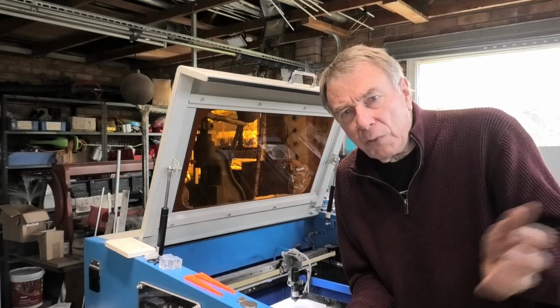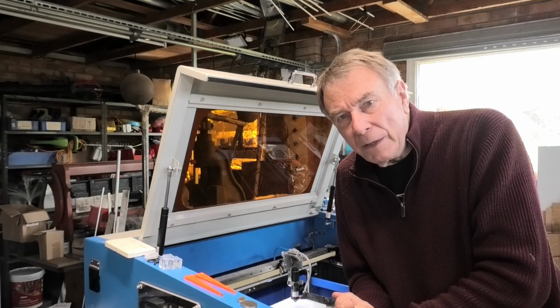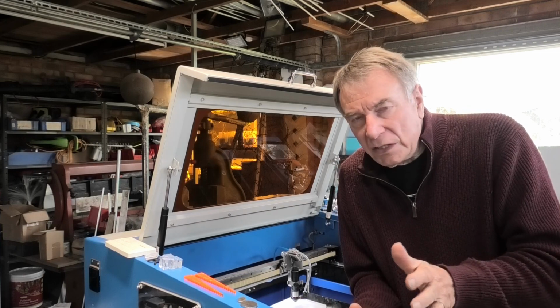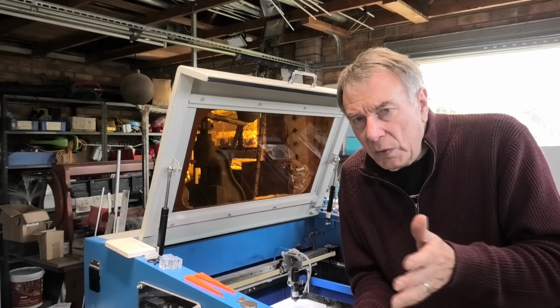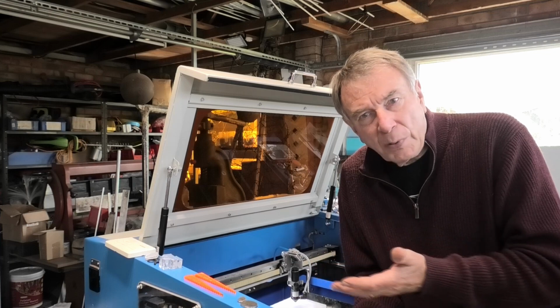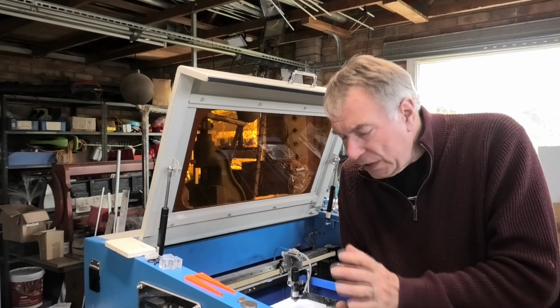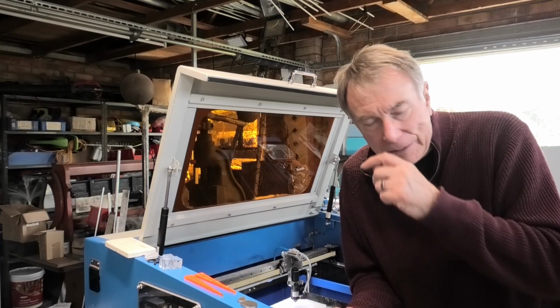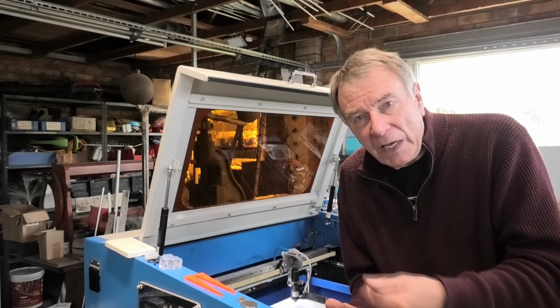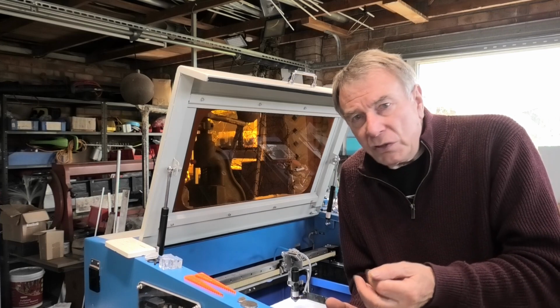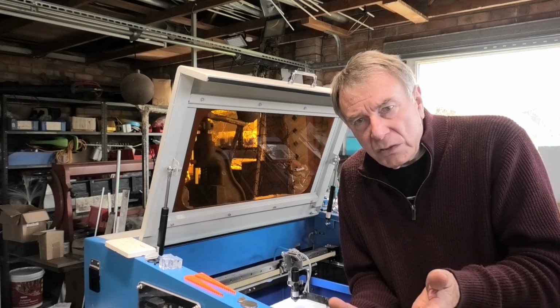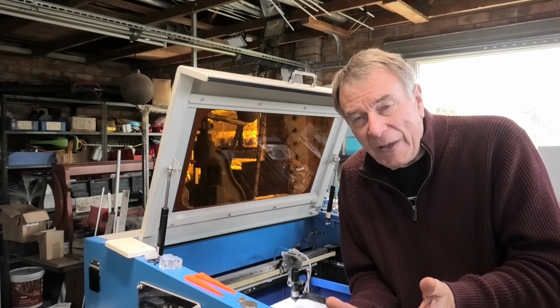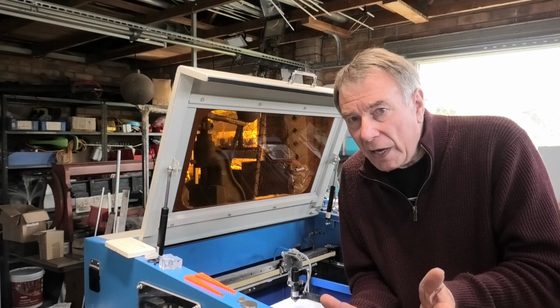Different wavelengths of light require different types of lenses. We're mainly going to deal in this session with the lenses we need for the CO2 10.6 micron wavelength light, because it is a rather special sort of light that requires special material for the lenses. As you get towards fiber laser and diode laser, you can use just ordinary glass lenses, which are much easier to manufacture, and you get a much wider variety.